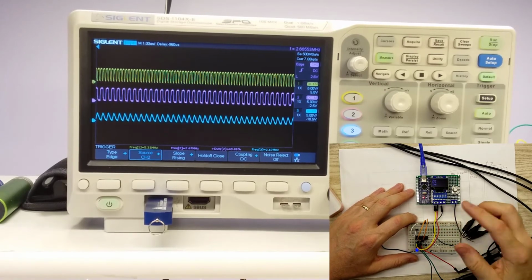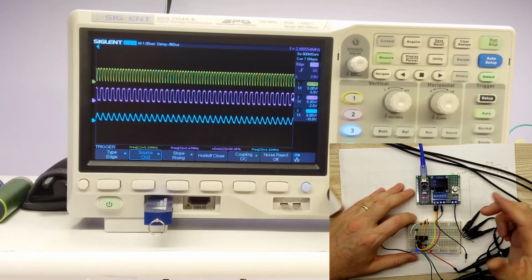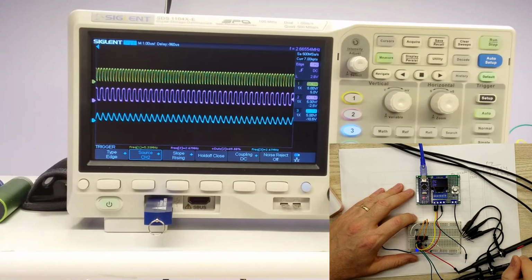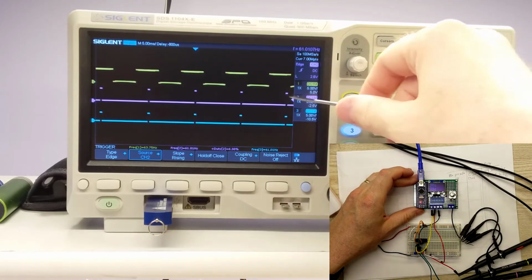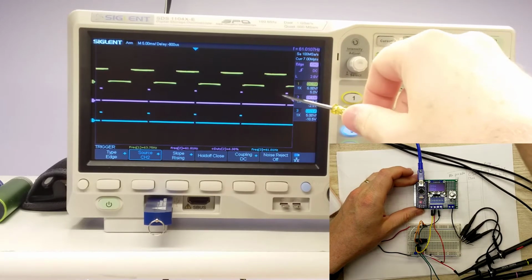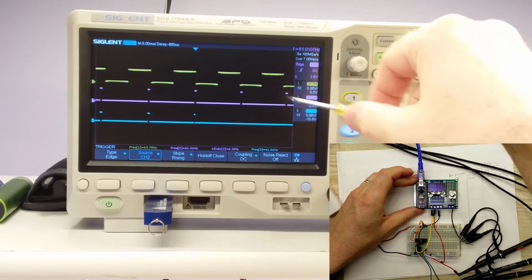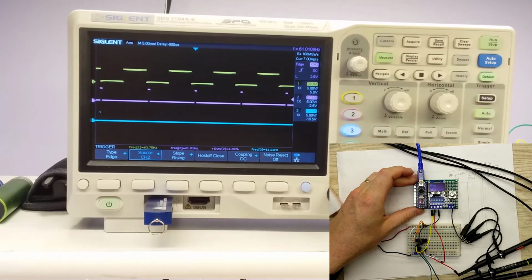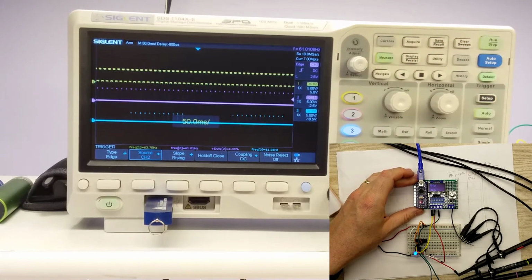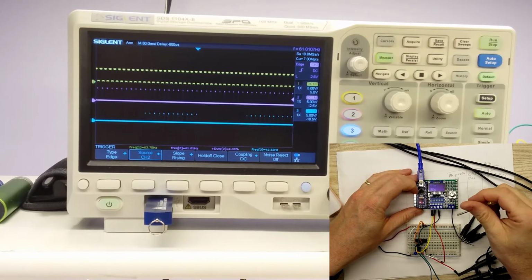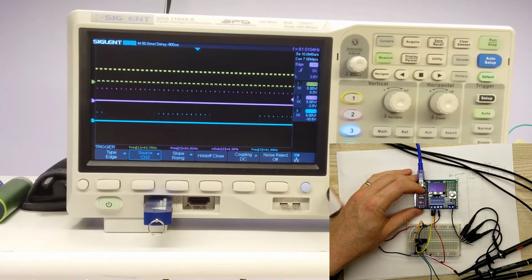So let's switch it over to this PWM line with the different frequency and see how it does when we start varying things. Now we're running at around 64 hertz, and we've got the B line, or the second input, varying on a little PWM on a different frequency. That's running at around 61 hertz, where the first input is running at around 63 hertz. And so you can see the output is varying a little bit as those are no longer overlapping perfectly. As we zoom out a little bit, you can kind of see that pattern as it goes through, but it's handling it just fine. Let's kick this all the way up to 5.3 megahertz.